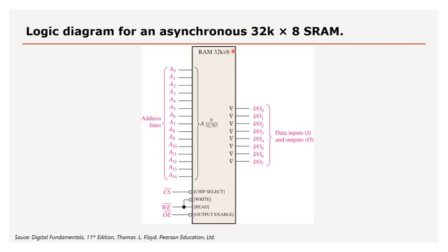That's the number of positions that you've got, and the width of the data is basically 8 bits. You'll always see that what you see here by 8 will also refer to the number of output pins on the specific device. So there are basically 3 very important buses in a RAM device, and that is true for all devices.